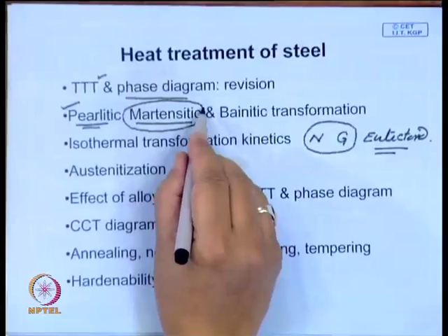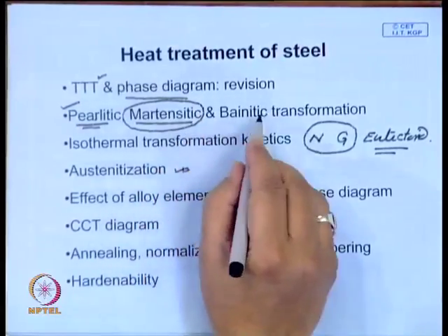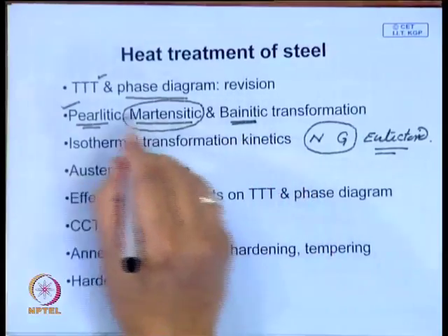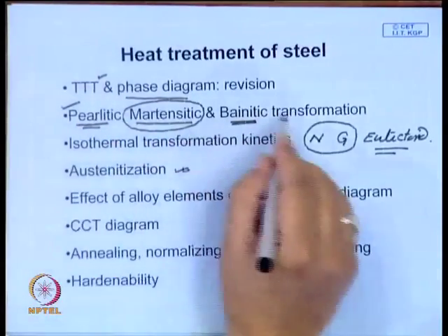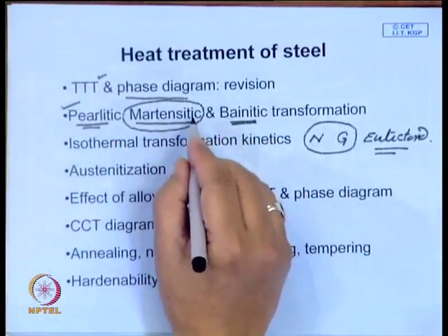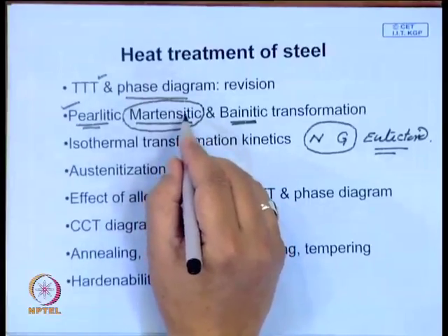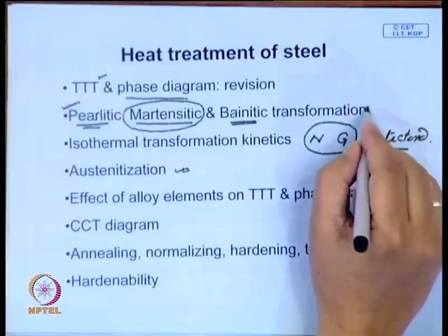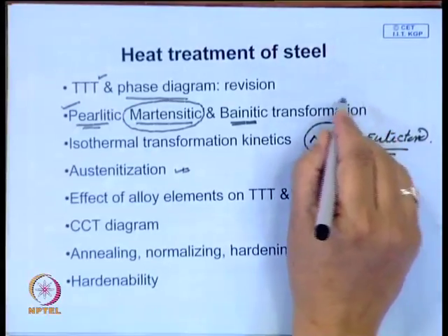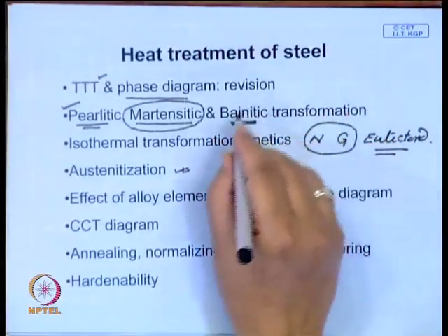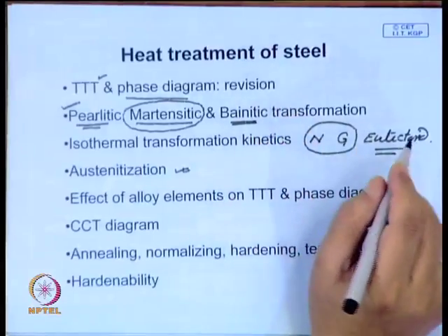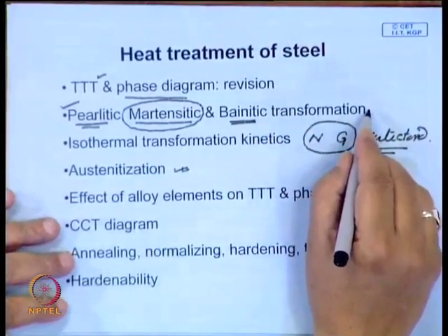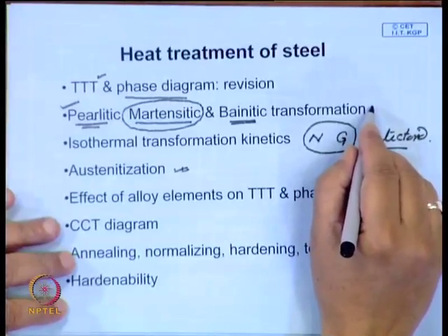We will see how this takes place a little more critically today, whereas Bainitic transformation has certain features which match with Pearlitic, and certain features of morphology which match with martensitic. But basically here some precipitation does take place. So, Bainitic transformation is a transformation where some amount of short range diffusion of carbon atoms is essential, that is the key.